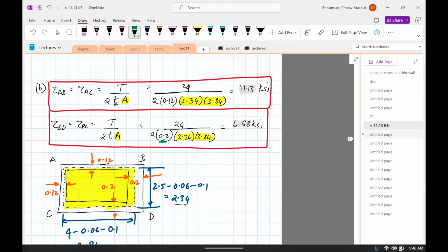However, when you increase the thickness, you increase the weight of the material. And when you increase the weight, there are other repercussions, like maybe it's used in an automobile where you have to carry that extra weight, and that's not good. So there's always a trade-off between increasing the strength and decreasing the weight. That always happens in design.